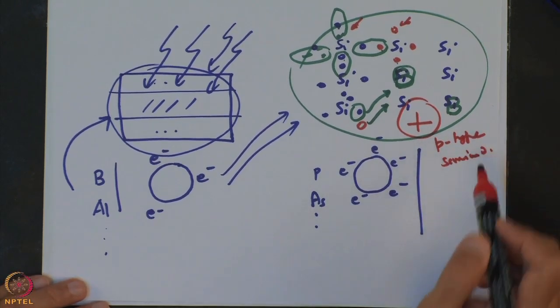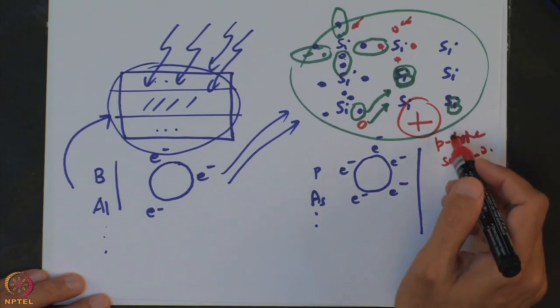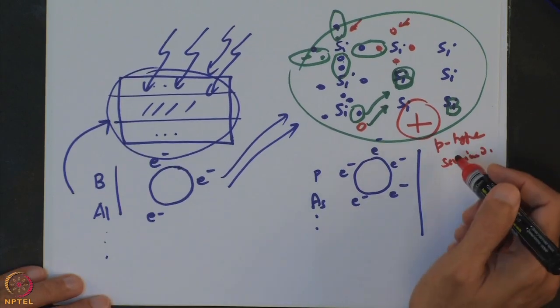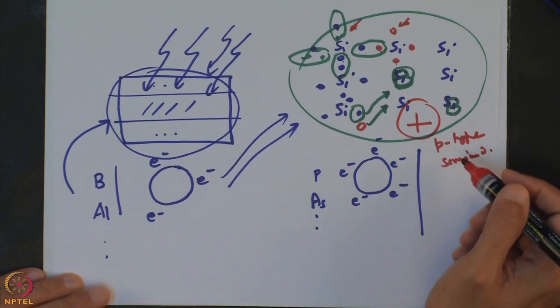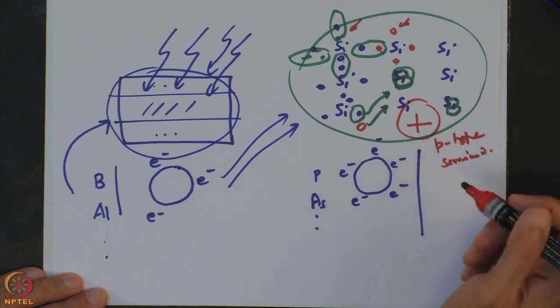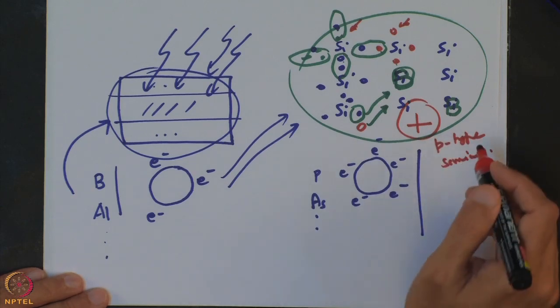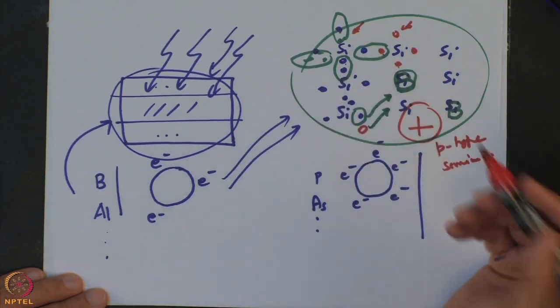It is an extrinsic semiconductor now, a p-type semiconductor, an extrinsic one, the one which has been adulterated, which has been mixed with impurities, or in terms of semiconductors we call it doping. So, it has been doped. An intrinsic silicon semiconductor has been doped with trivalent impurity to generate p-type semiconductor material.